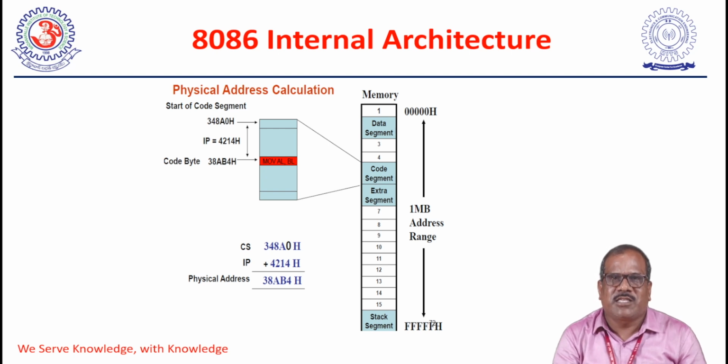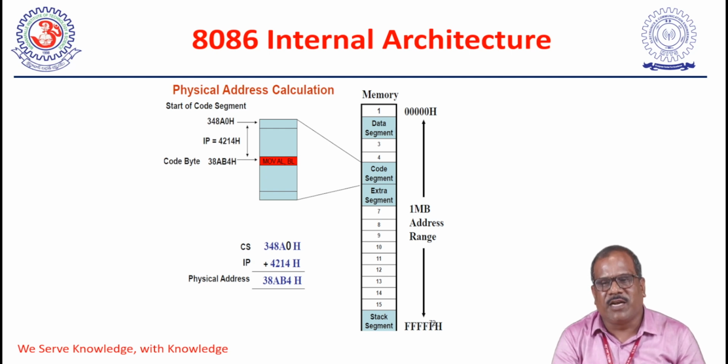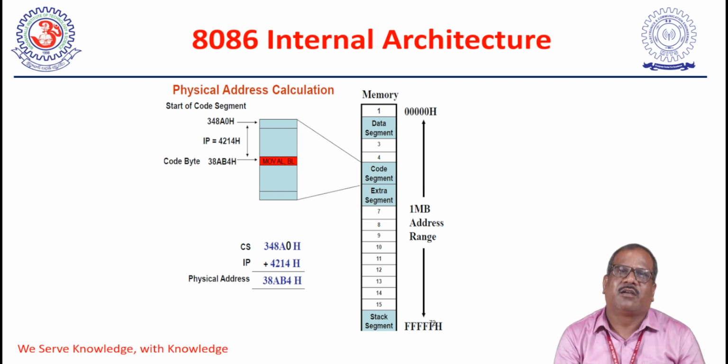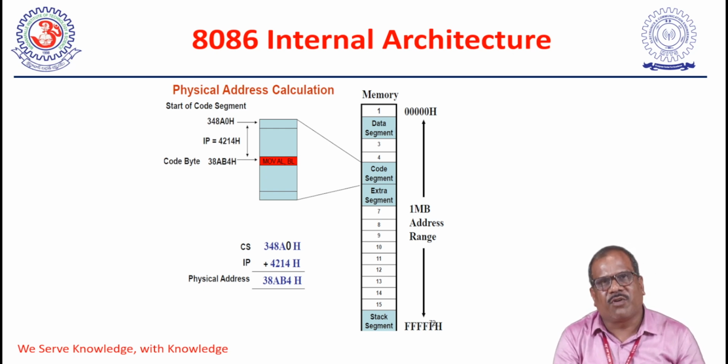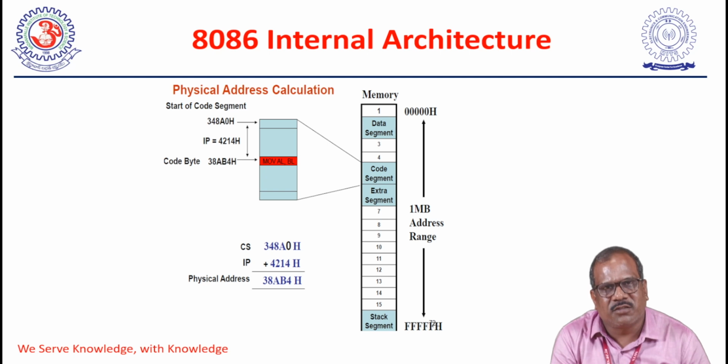Each segment can use continuous addresses or start from some other location. For example, the data segment can use location 0 up to the 64 KB end address, for example 40000 to 4FFFF. You can assign the next location to another segment, or start from some other range.